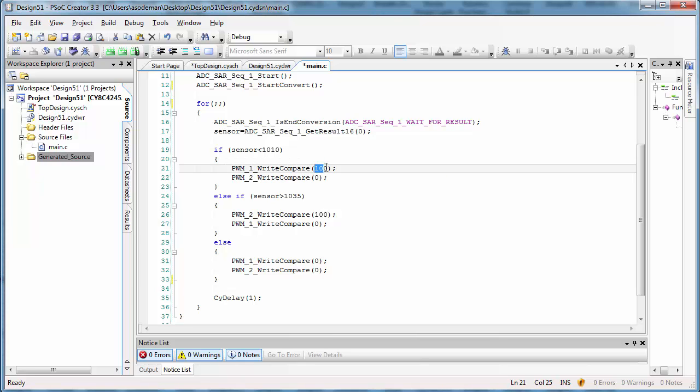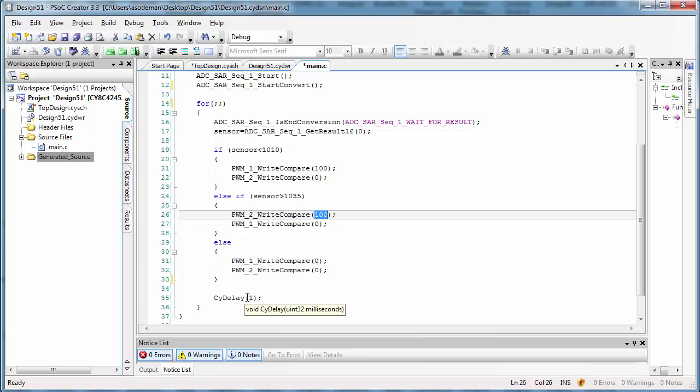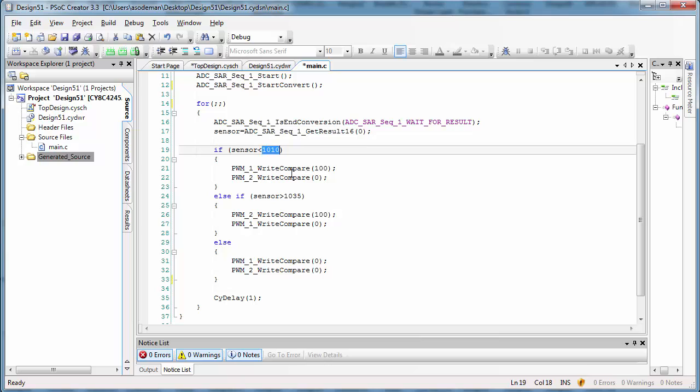One thing that we changed is we made the motor move slower. Another thing we changed is we made the loop time faster so that we checked the position of the sensor more frequently. The third thing we changed is we made the desired position have a greater range of where it could be and still turn the motors off.